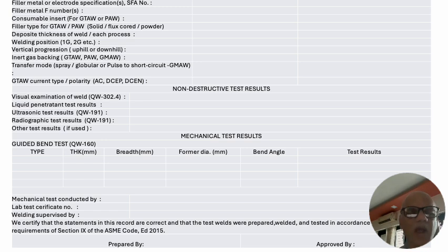And that is where I have stressed in each of these 3 documents, which are taken as very simple, and just quickly it is being done and announced that we have done all the necessary work now, and we don't have to really worry about it. So don't really engage in this kind of shortcuts when it comes to welding. Even if it is a simple carbon steel welding, please do mock-ups, please do a thorough WPS, PQR, WPQR qualification. Gain confidence, you will enjoy your job when it is on the shop floor, and you will deliver it on time.